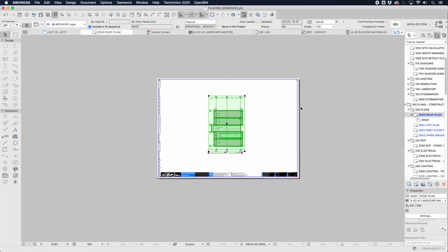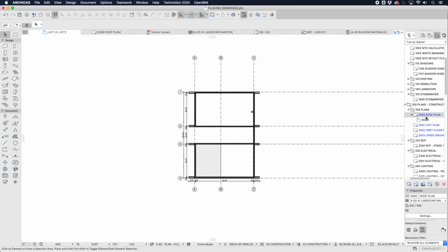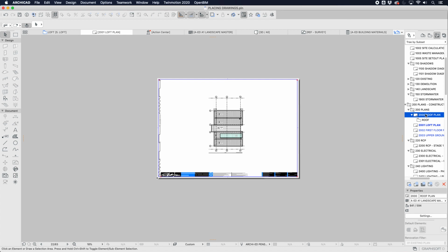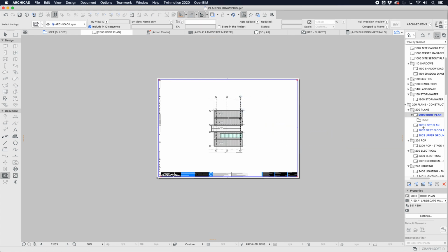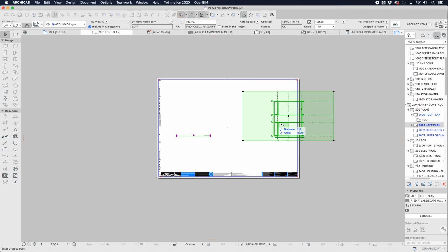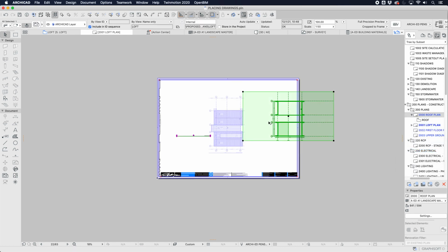In order to get this drawing exactly in the right place, we could bring it in. Let's pick up the settings as it was before, because that's awkward. Alt, pick up settings, loft, bring it in. And we can use trace reference. So let's turn on the trace reference. That's this little box here, or two boxes. We can also just right click and say show as trace reference, and that's going to choose to reflect that the way that we want it.